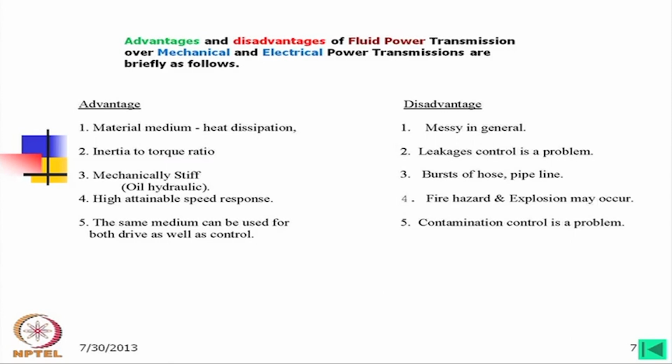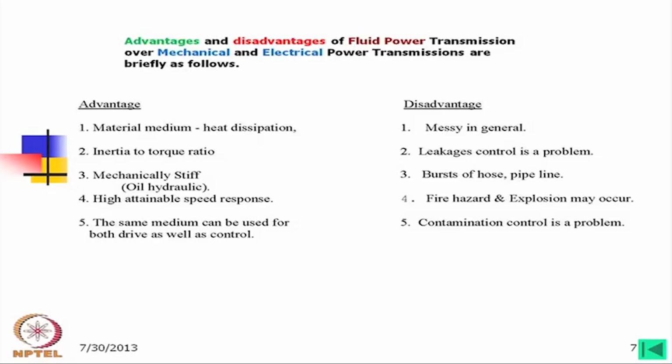Thirdly, mechanically stiff, particularly oil hydraulics; if we consider the bulk modulus, which is equivalent to the stiffness of metal, it is very high. Fourthly, high attainable speed response. The response through the fluid is transmitted very fast. Fifth is the same medium can be used for both drive as well as control.